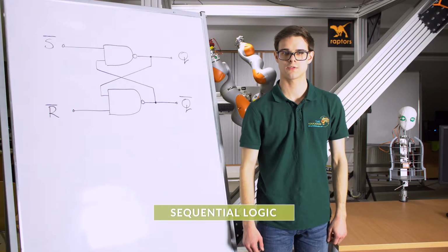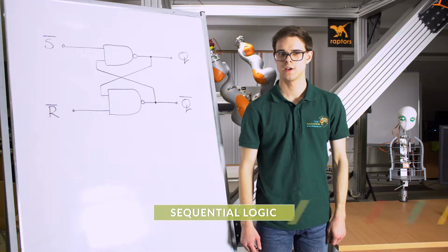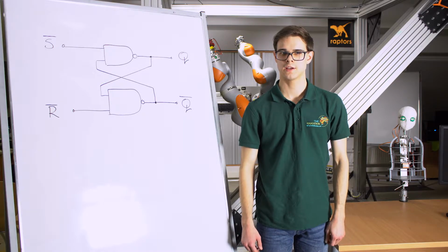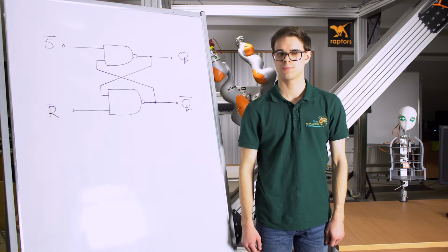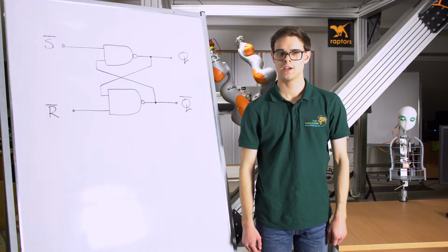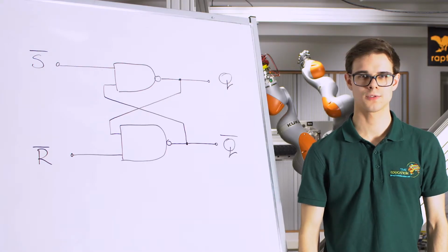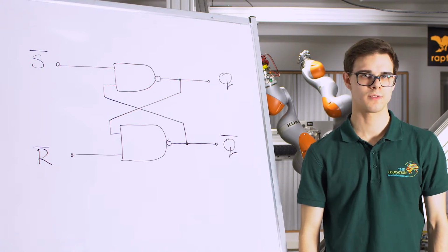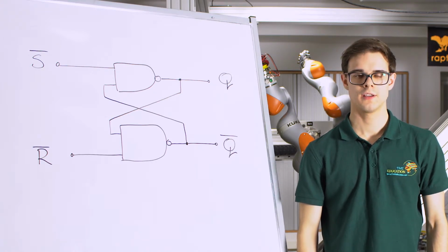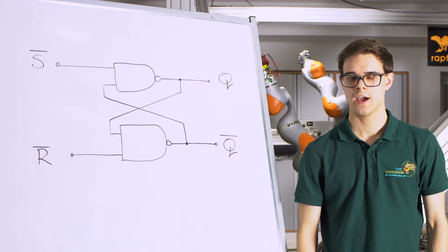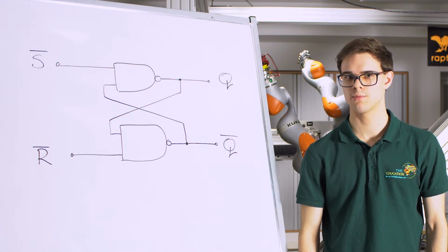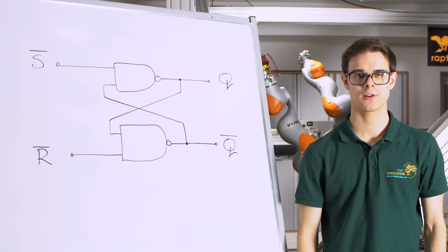The previously mentioned logic circuits are combinational systems, which means that their output state depends only on the logic state of the inputs. However, there are also more complex logic systems in which the output state depends not only on the logic states of the inputs, but also on the internal state of the system. Such systems are called triggers, and they can be built based on logic gates. They are used to memorize the current state, and they often have an additional input to synchronize changes with the clock signal.